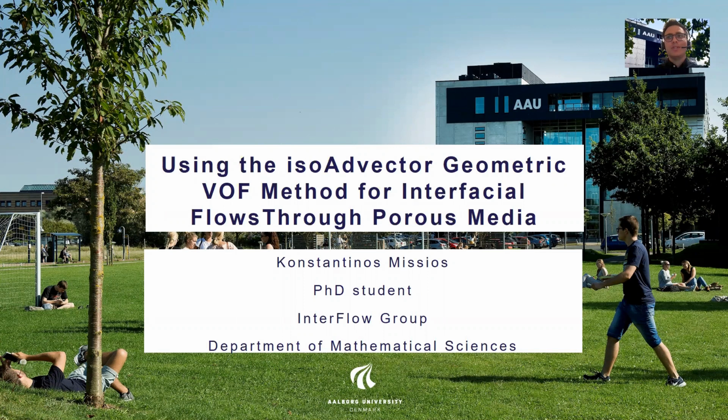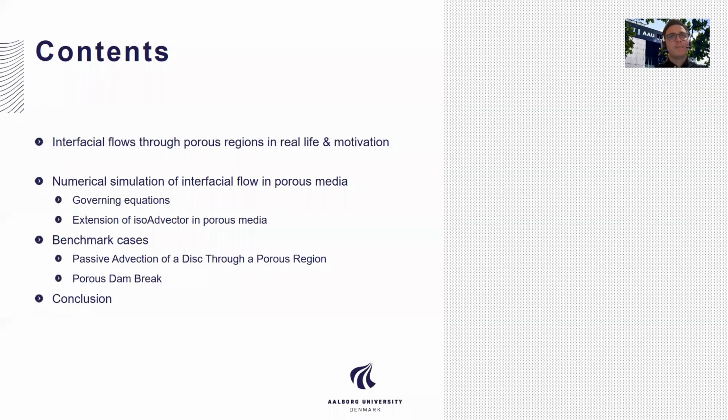And today I'm going to be presenting to you our recent development on using the isoAdvector geometric VOF method for interfacial flows through porous media.